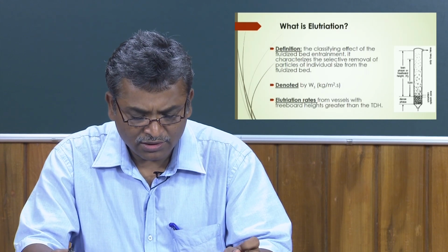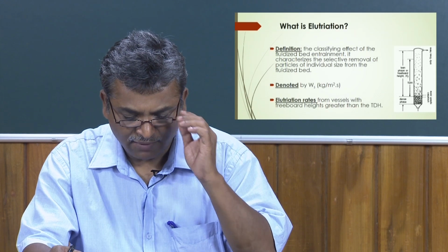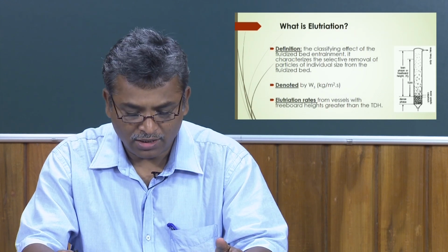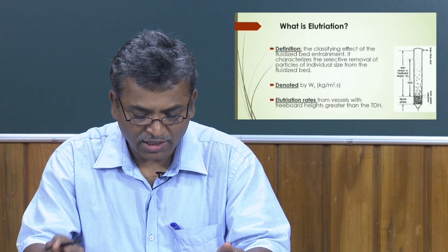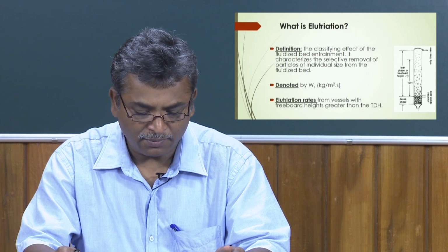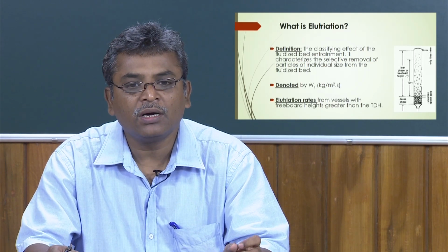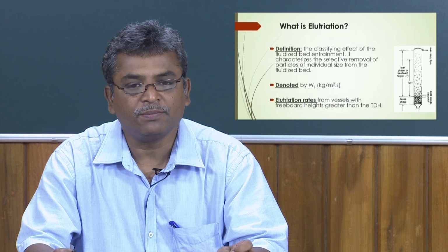Elutriation is defined as the classifying effect of the fluidized bed entrainment. It characterizes the selective removal of particles of individual size from the fluidized bed.